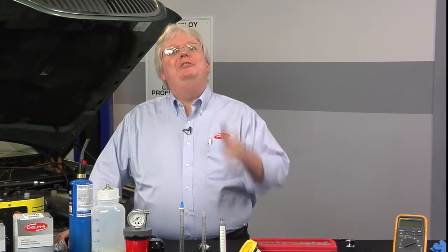Okay, Dave, our first question is from Pete, and he asks, what is the difference between the PID short-term fuel trim bank 1, and short-term fuel trim bank 1 sensor 1? They are often used on the same vehicle, and do you add all 3 together to get total fuel trim? Wow, Pete, that's a great question, and I wish I had an absolute definitive answer. My gut tells me that they're basically the same PID.